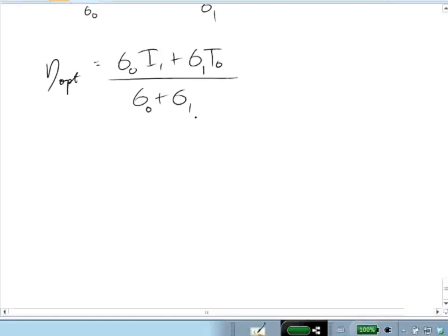So one of the things that you'll be exploring in your validation is use of the optimal threshold. And one thing you'll find is that you really shouldn't use the optimal threshold because the optimal threshold will not actually give you the minimum bit error rate because of various imperfections in your simulator, the finite bandwidth of your simulator, many factors. So when you get the MATLAB code for the homework, what you'll find is that we use the theoretical threshold as a starting point, but that we actually use a numerical technique to find the optimal threshold. And in the homework, we'll try and develop what would be some of the reasons that this might be the case.